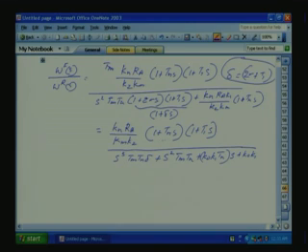Now, this 1 plus Tn s into 1 plus T1 s, these zeros, we can take care of like the current transfer function by appropriately giving a delay to the reference input. So, the transfer function to be finally optimized for our closed loop control is this one.